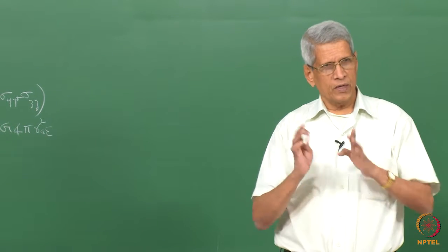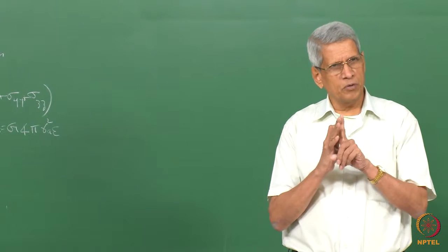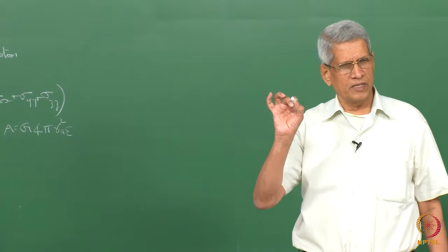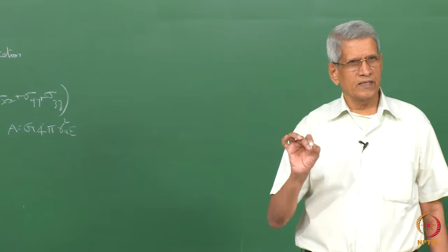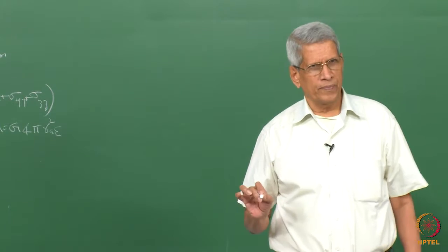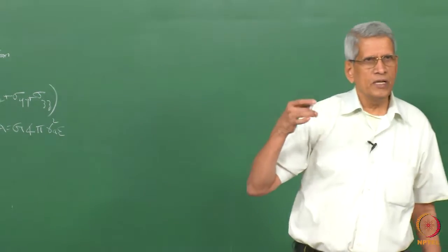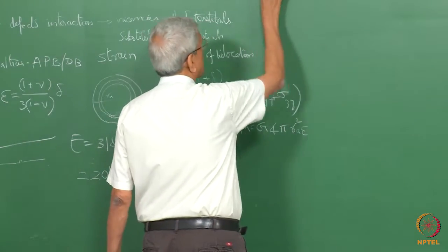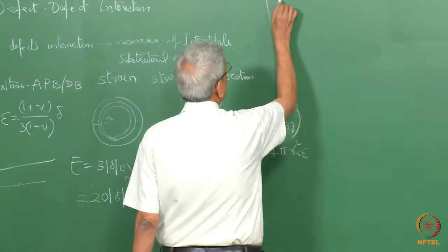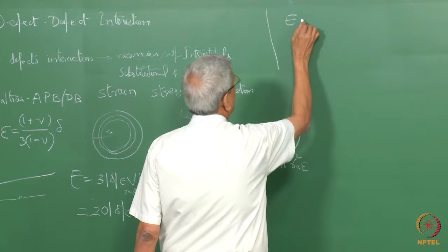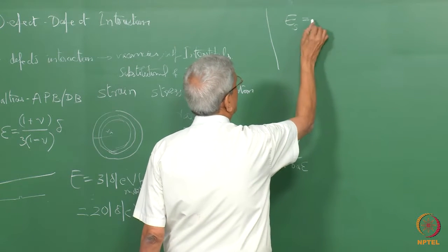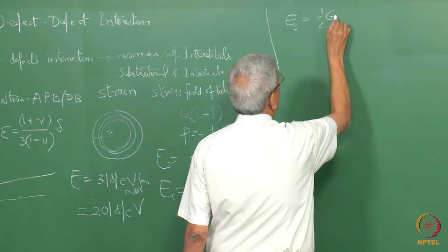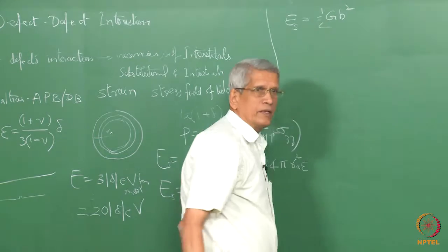When they interact, there is going to be a modulus effect, where when it reaches the dislocation, that segment, if it is lying there, has a modulus which is small. This is going to be there even in a material where a second phase particle is there. If a dislocation moves in a material, we know that the self energy of the material is given by this formula, roughly half G b squared, correct?